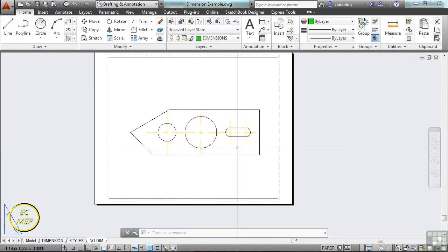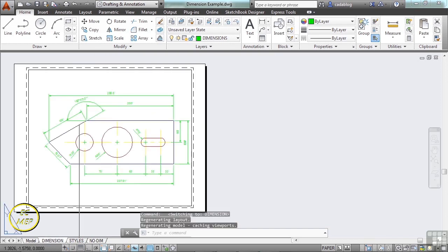You can create dimensions for a variety of object types in many orientations. Linear dimensions can be horizontal, vertical, aligned, rotated, a baseline, or a continued dimension, which is a chained dimension. Dimensions can be associative, non-associative, or exploded. Associative dimensions adjust to changes in the geometric objects that they measure. I recommend that you always use associative dimensions, especially if you are placing your dimensions in paper space. I'll show you some examples here.